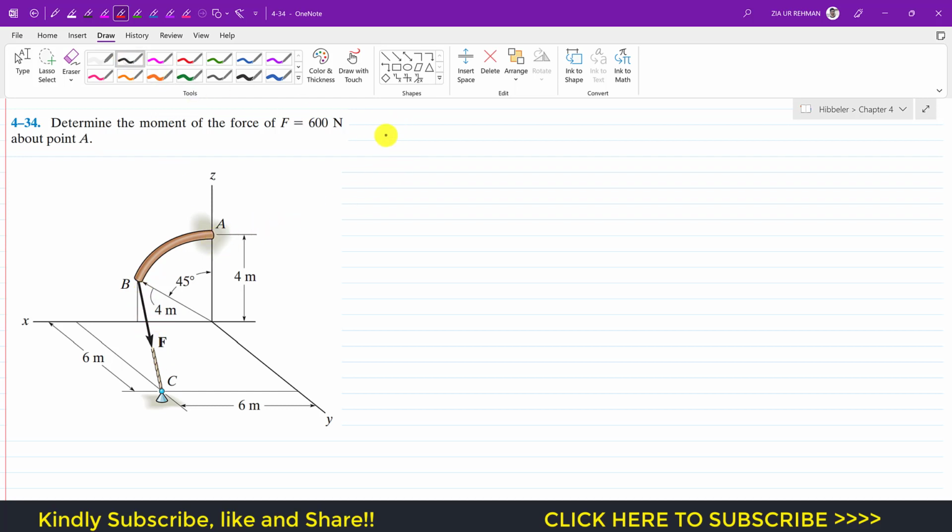As we know, the moment of a given force can be determined about any point by using the cross product. So we can say that the moment about point A will be equal to the cross product of the moment arm with the force F. So we have to define the moment arm. We can take the moment arm from A to B or from A to C. Both will give us the same answer, right?